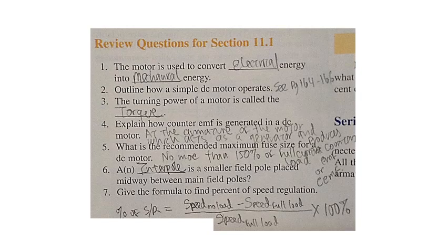The purpose of this is to change the direction of the voltage or current induced into each side of the commutator. So at one point, when the commutator is at a certain position, voltage and current flow in one direction. When the commutator turns half a turn, voltage and current are flowing in another direction, depending on the contacts of the brushes with the commutator.